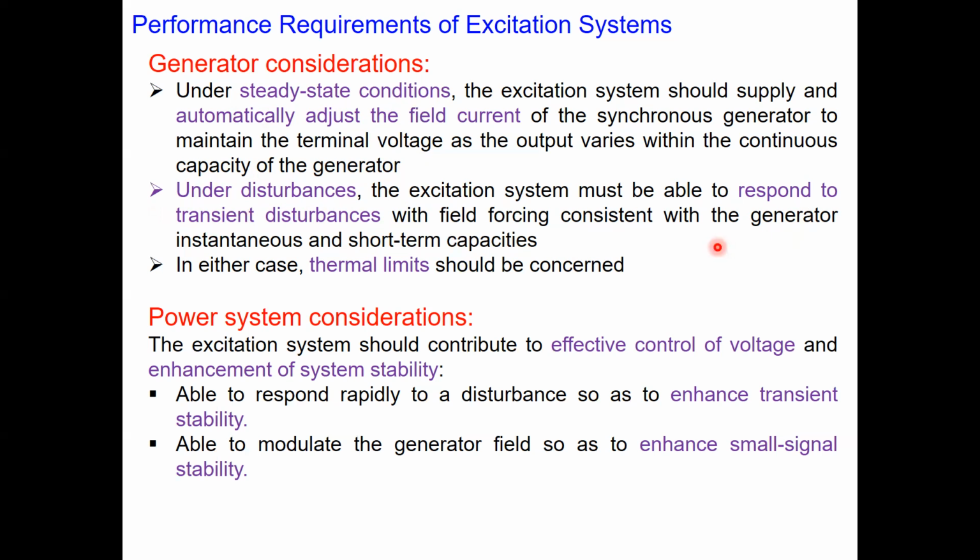Although, just see, do you know that the field flux you have in the air gap, do you think that it can be changed suddenly? What is your comment? Field flux distribution. In fact, not. Yeah, there is always some amount of delay if you want to vary the field flux in the air gap of the machine. All right. But still we want the change in the field flux response to be fast enough so that it can get the system restored whenever you have some disturbances.